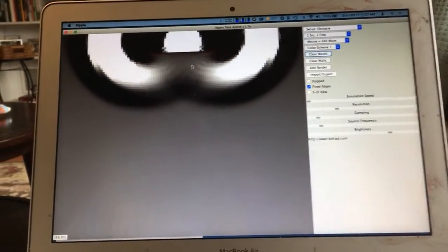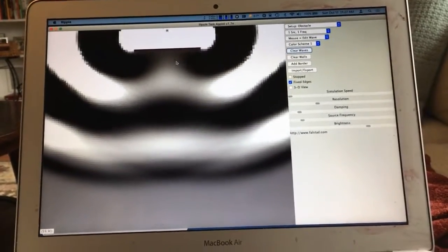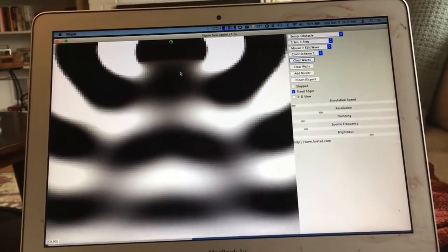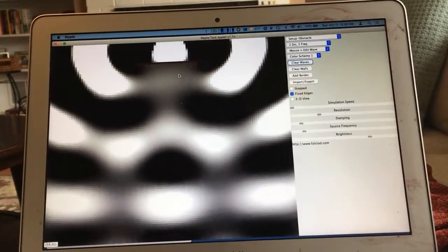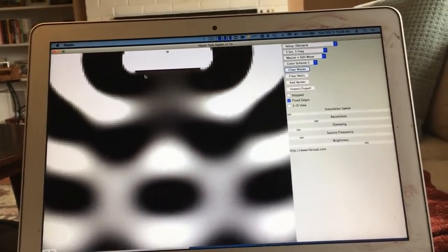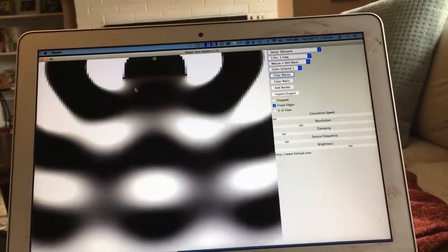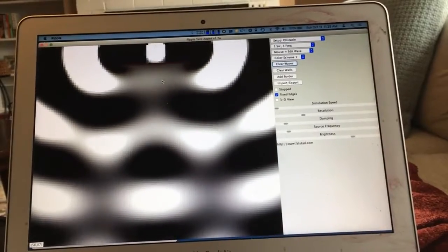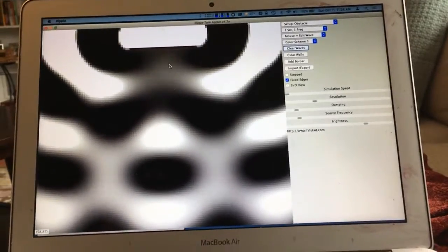So again, it's always much more difficult to block low frequency noise than it is to block high frequency noise, for a number of different reasons. In one case, with our partition between two rooms, it's because high frequency sounds are more easily reflected and low frequency sounds are more easily transmitted through a barrier. In this case, it's a totally different phenomenon. It's diffraction. The longer wavelengths, the lower frequency components, are better able to bend around the barrier. The higher frequency, shorter wavelength components bend much less, so you get a nice clean shadow region.